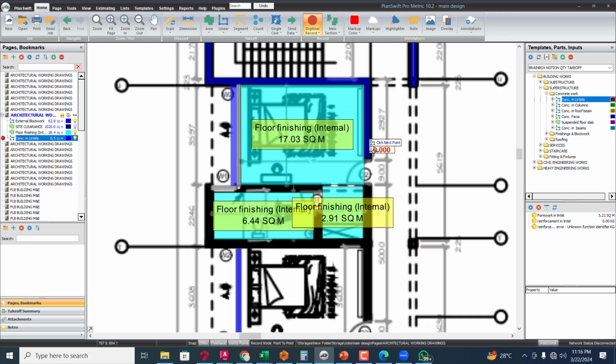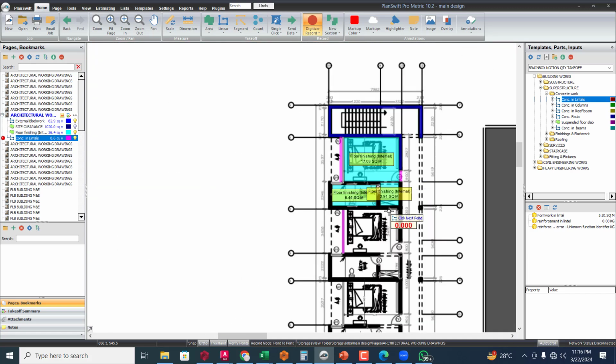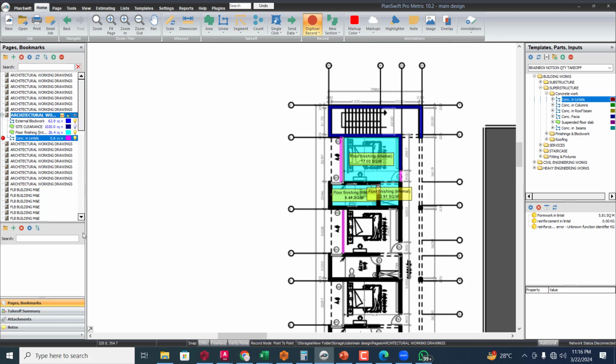So I have one here, and I will double click. So however, this is basically how to come about that lintel. Now if you look at this from the left hand corner of my screen at the top here, you realize that that has been taken off. So this is 0.6 cubic meters so far, based on what we have taken off.